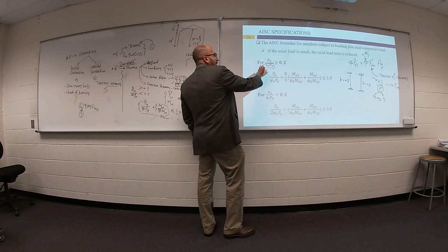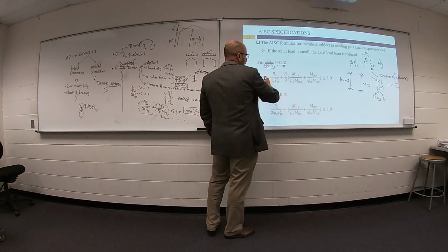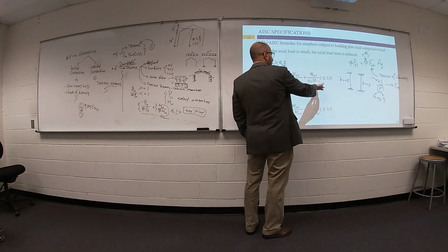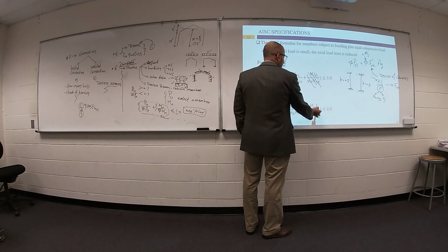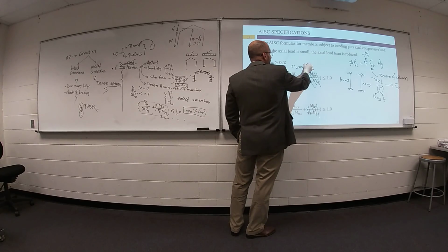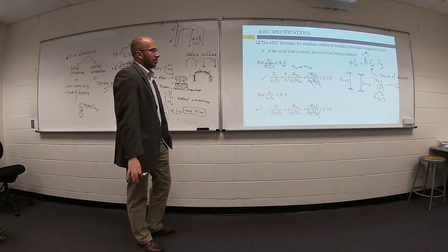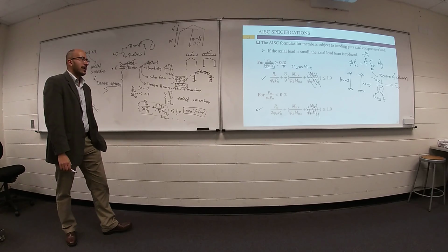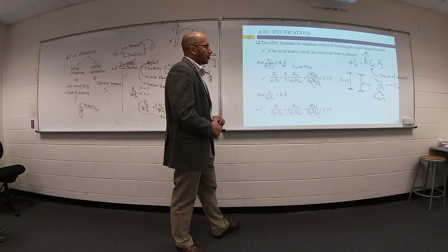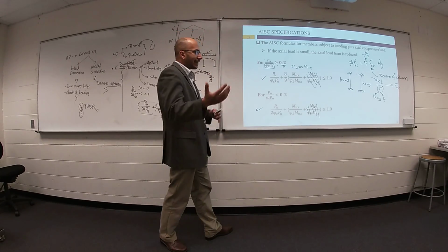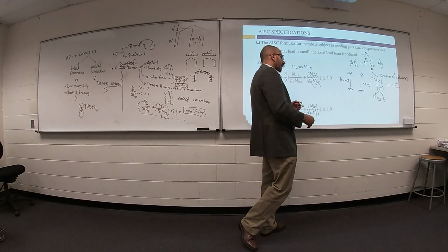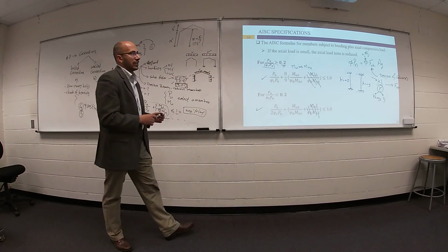What is this value? Greater than or equal to 0.2, I will use this equation. Smaller than, I will use this equation. Actually, we don't have My, so this term will be cancelled. This term will be cancelled. The only moment we have is M ultimate X, your M ultimate from RISA. Then go ahead and get your value here. Your value must be smaller than or equal to 1. If your value is 0.9, you will say safe and economic. 0.3, safe but not economic. 1.1 or 1.5, say unsafe, we need to increase our cross section.